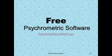Dry bulb, 74, and a dew point of 50, what was that? 54. You can just enter those two values, and that'll tell you what the relative humidity is under those conditions, if you're able to achieve those two conditions in the data center. But I know if I try to switch off from this webinar to the software, something's going to screw up and I'll lose you forever.